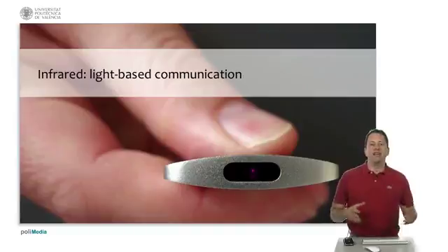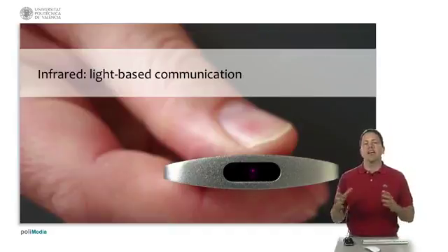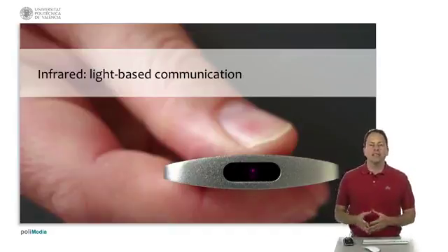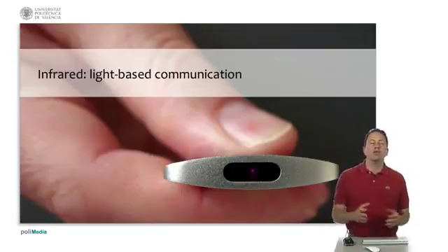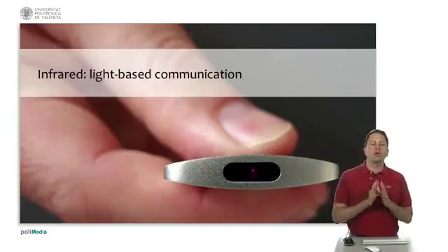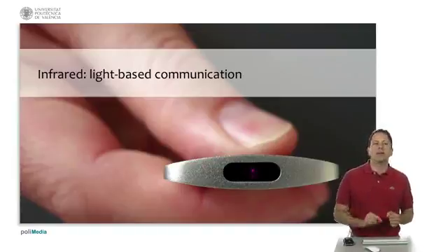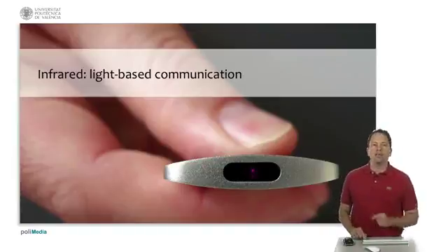You can also find visible light communication equipment and free space optical communications equipment that rely on LED or lasers, and they can achieve gigabit per second speeds up to a couple of kilometers. So to link two buildings, if you cannot put a cable or it's difficult, you can use one of these two technologies to connect one with a high-speed link to the other.